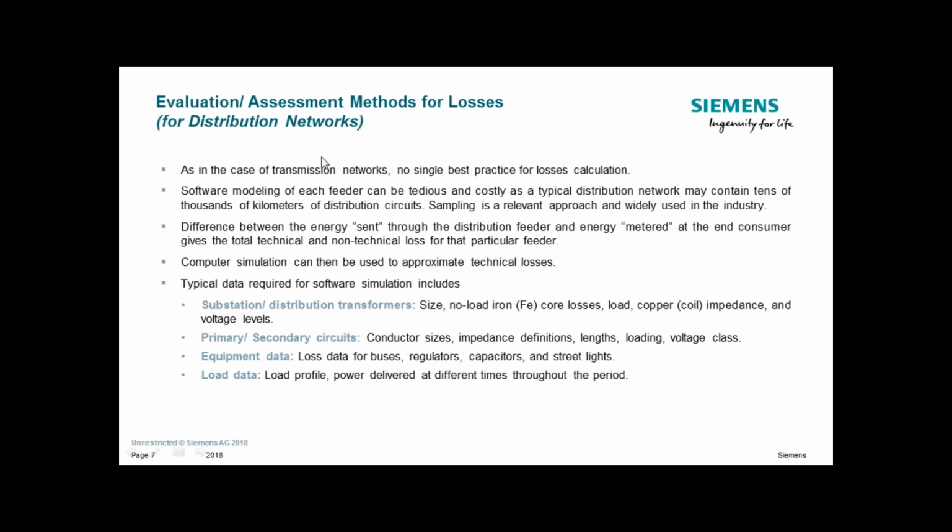Another challenge is that the distribution network is so big, like 30,000 small distribution substations. When you start modeling and simulating, analyzing the data is tedious work. It's not easy, because for the modeling you need accurate data for 30,000 transformers, and it is really challenging to get all those data. Most of the time we say, okay, this is typical data used in countries, but this does not really give accurate results. These are more reliable results, but not accurate results.